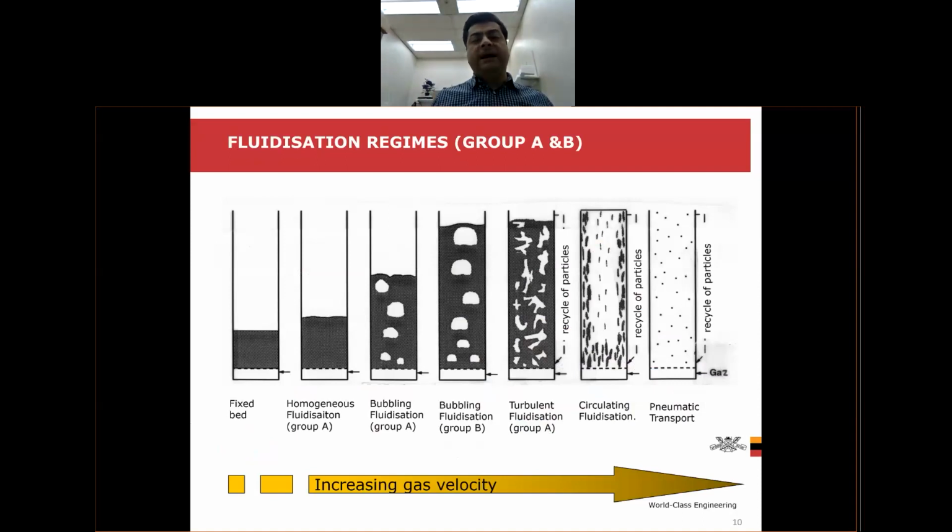But fluidized bed reactors essentially could have different regimes. In other words, they could have different flow patterns. Let's, for example, assume this tank on the left. If you apply a gas with the velocity of Vg, or sometimes people show the velocity by U, doesn't matter, Ug or Vg, gas velocity. If you apply a gas velocity very slowly, you might end up in a situation where the powders are not moving around. The bed is still a fixed bed.